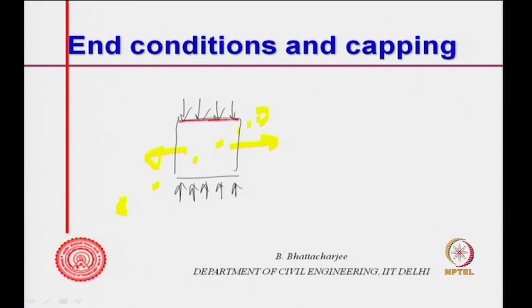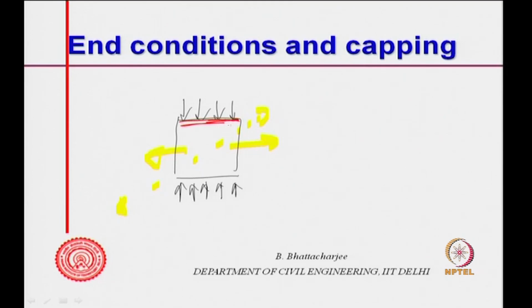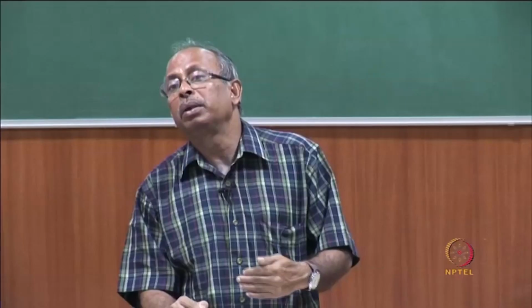Now, the movement of the material is restricted by the friction between the machine plate and the specimen. So, there is a kind of force acting like this, frictional force, which will not allow this movement. Similarly, here this is a kind of frictional force which will not allow it to move along this direction. So, there is a surface, but then surface material is in contact with just the bottom next layer of concrete.